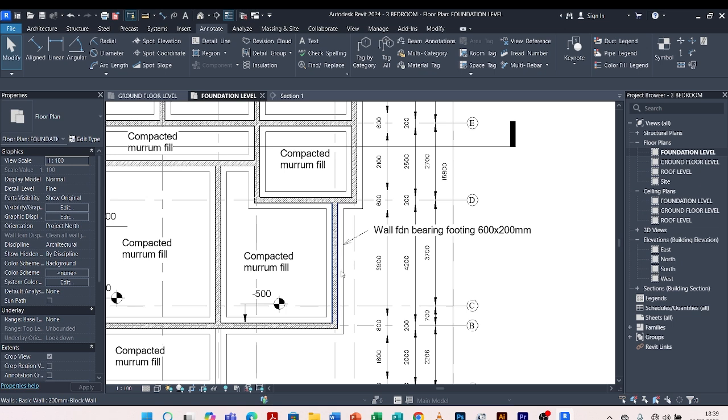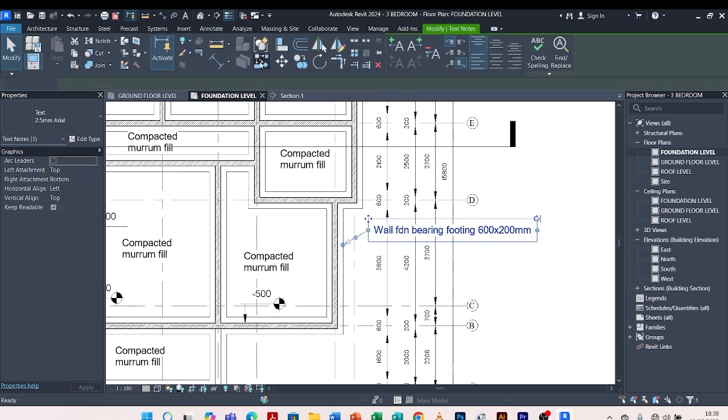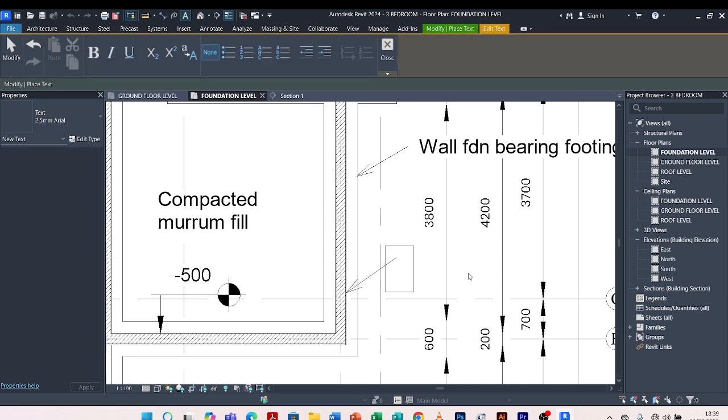Then also I'll need to name the plinth walls. I come click on this. I create similar. I come pick off the plinth wall. I'll name this as our plinth wall. Then for the thickness, 200 millimeters.